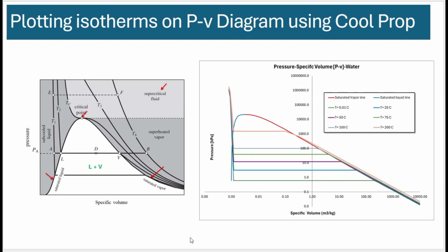You could use the same method for creating the pressure versus specific volume of water and the isotherms on this plot. You can see even on this plot, the pressure is constant inside the dome and it shoots up really high in the liquid region. This is the liquid vapor mixture region and this is the vapor region, right?